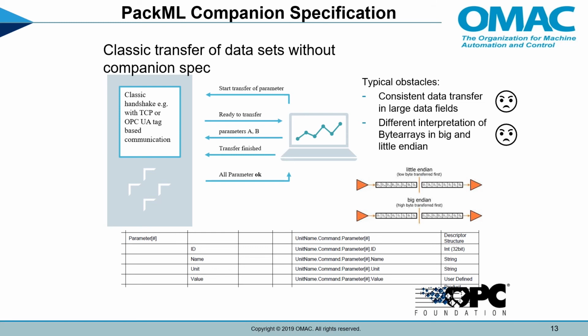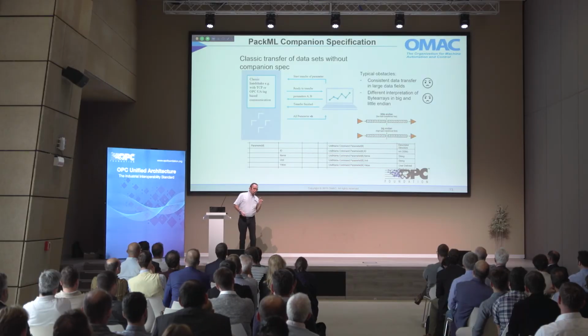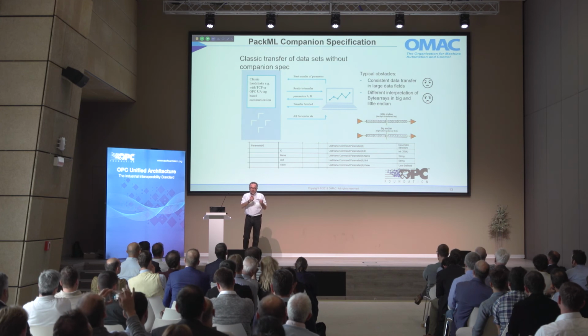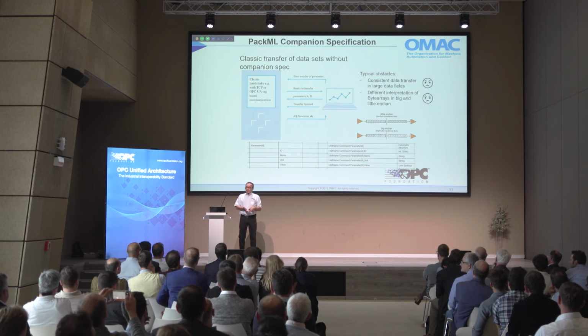If you want to transfer a larger amount of data, so that the data are consistent to your application program and also consistent when it gets into your other application program. And maybe somebody knows of big and little endianness, so the bytes and words are shifted, and you write one and get billions back on the other side if you have that wrong.